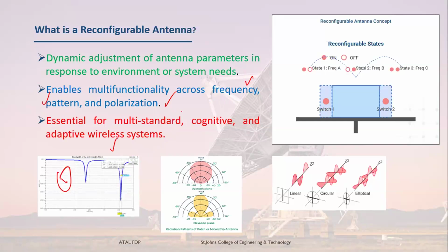The second one, as you told, is radiation pattern. Radiation pattern is generally based on the structure of the antenna, or sometimes we can change the phase. When I use an antenna array, as people who have taught antennas might know, the radiation pattern can be changed dynamically. The phase of the signal given to each independent antenna will change the radiation pattern, not only the direction but also the shape. So how do we change it dynamically?